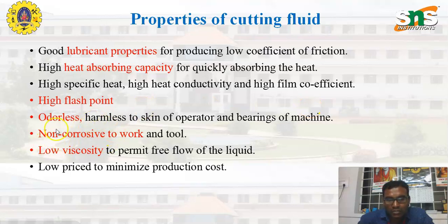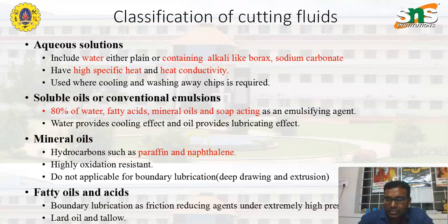Next, it should be non-corrosive to work and tool. It should have a lower viscosity, and the price of the cutting fluid should be low in order to minimize the production cost. Next, we will discuss the different classifications or types of cutting fluids one by one.